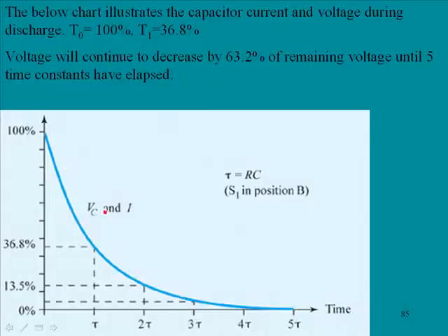You'll notice here the voltage and current are going to be proportional. In this case, the switch is now in the position where the cap can discharge through the resistor, and the voltage and current will be directly proportional because now the capacitor is in effect the battery, and it is providing all of the voltage and current for the circuit, and so they will decrease.